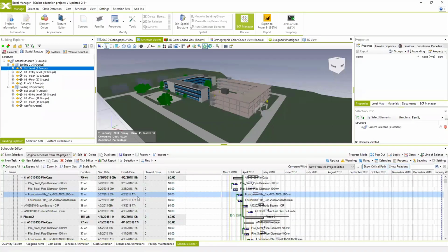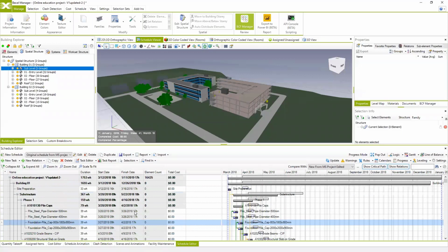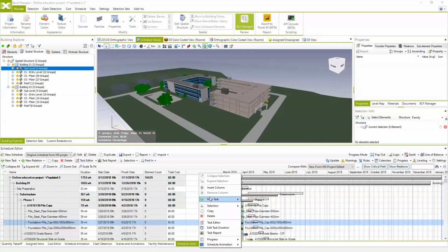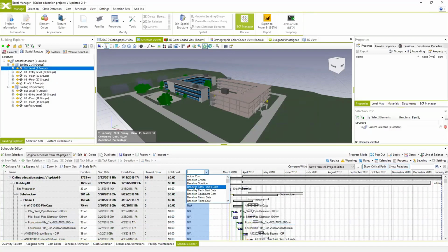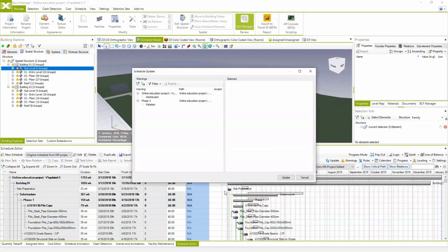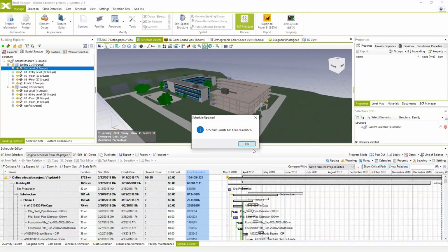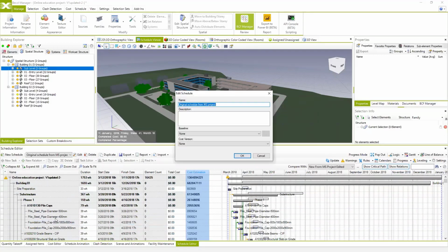And then if you link your BIM model to your cost version, even though it's imported from MS Project or Primavera, I can show you the column which actually shows the cost imported. So this is the cost estimate from the schedule, I think. And here, within the total cost, we can relate this schedule with a specific cost version.